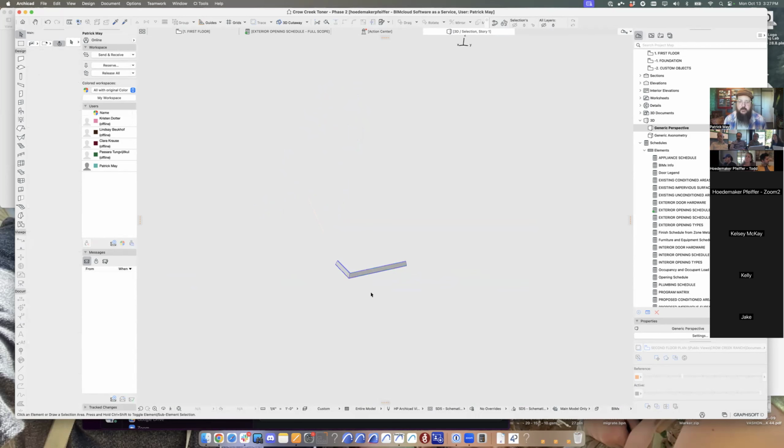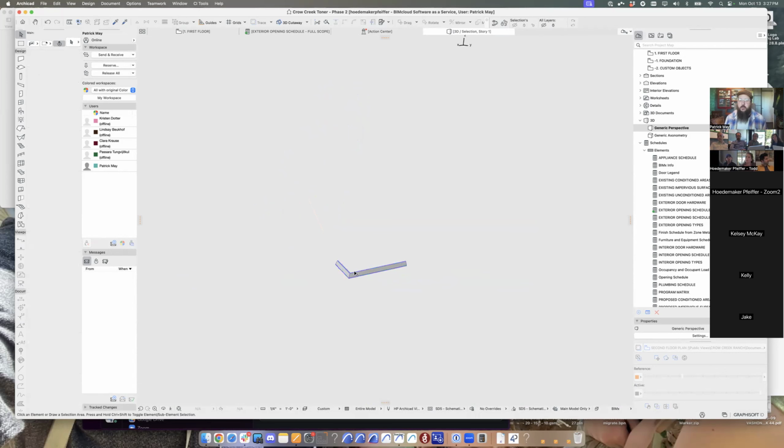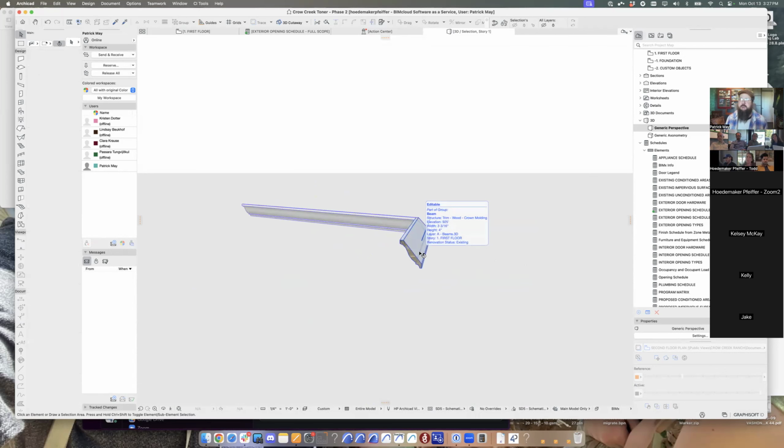But for right now, backing up, you're saying model with beams, not with complex wall. If it's anything that requires an extruded shape, the wall works great for simple extrusions. If it has more complexity, either model it with extra walls or model it with extra beams to augment, supplement the wall shape.